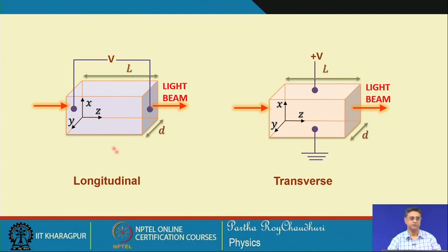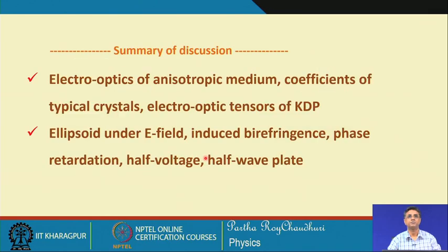In the next section, we will continue our discussion with this longitudinal and transverse mode of operation of this KDP crystal, and we will see how we can use both these configurations for light modulation and switching in terms of the amplitude modulation, phase modulation and also this transverse configuration to make use of this longitudinal amplitude and phase modulation.